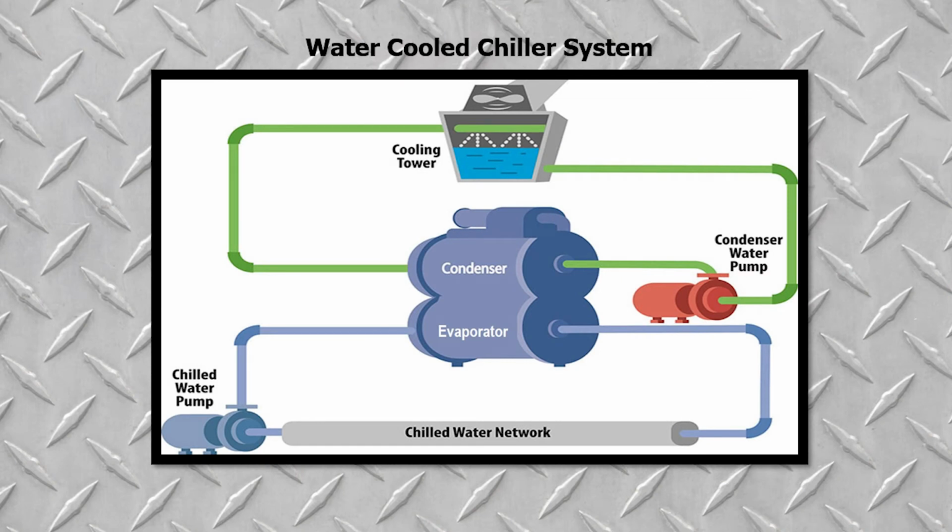And there's a very important reason for this. Not only do we cool with water effectively, but we're able to lower the temperature more than we could with ambient air by using the physics of evaporative cooling. In a cooling tower, the evaporating water takes out enough energy so the actual temperature can drop below the ambient outdoor temperature. Amazing, right? And it's done, okay?